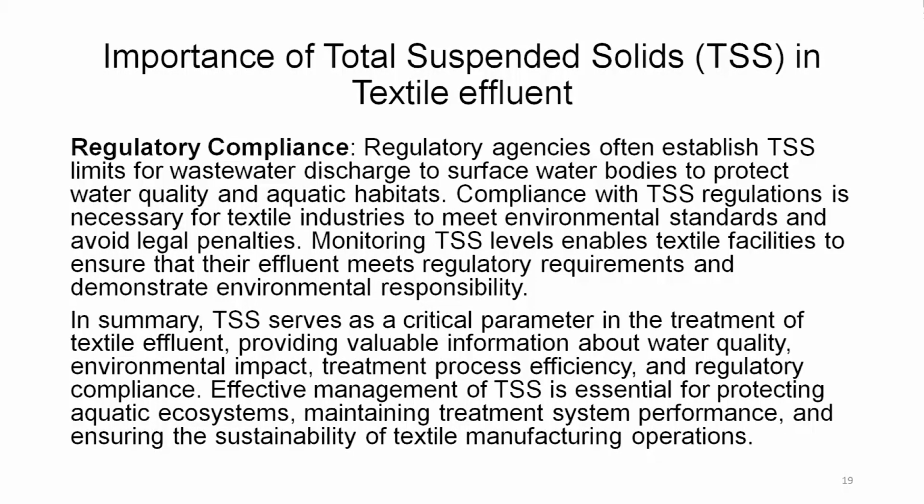Regulatory compliance. Now, everywhere there are regulatory norms for each of these parameters, and this we should understand and know very well. Regulatory agencies often establish TSS limits for wastewater discharge to surface water bodies to protect water quality and aquatic habitats.